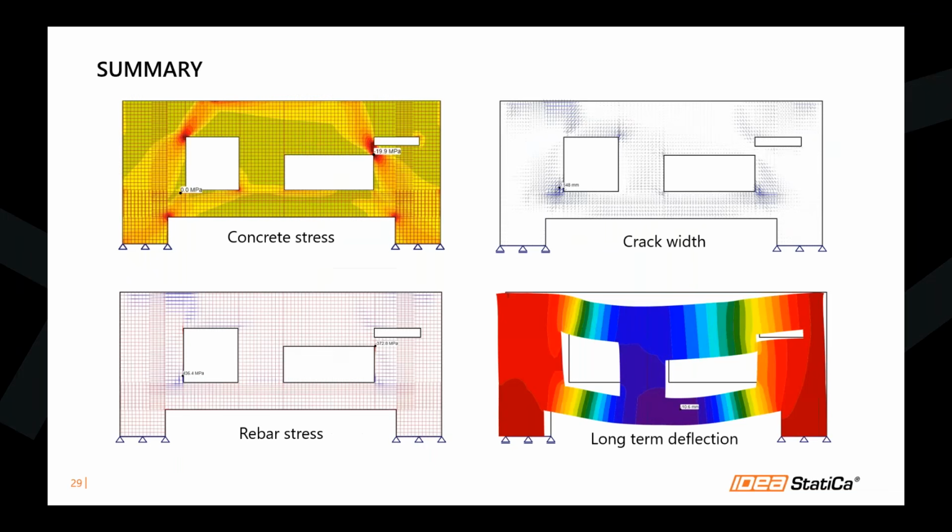So yeah, you are using IDEA StatiCa Detail. You can see concrete stresses, rebar stresses, crack width, even long-term deflection. So these two on the right, the SLS, as I mentioned before, will not or can't be provided by traditional hand calculation method.